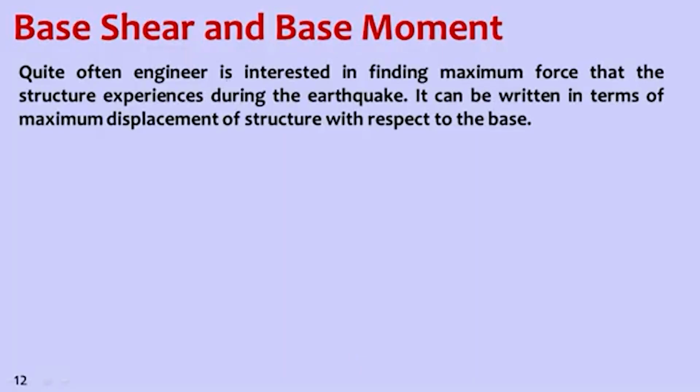Then it is very important for us to calculate the maximum forces. What we got from the response spectrum chart is spectral displacement, spectral velocity and spectral acceleration. But for designing a building, what we actually want is forces. We need base shear and then the distribution of base shear over the height of the building. So how do we calculate base shear and base moment? Let's discuss that. Quite often an engineer is interested in finding the maximum force that the structure experiences during an earthquake. It can be written in terms of the maximum displacement of the structure with respect to the base.